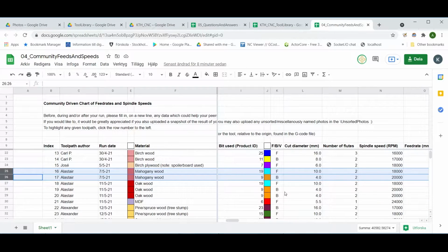And so as to make sure that the finishing of the model that we intend to mill gets an equally smooth or perhaps even smoother surface, we can use a 3D parallel toolpath with perhaps a stepover of 1mm instead of 2mm. 1mm stepover will of course lead to double the time as 2mm stepover would require, but this can be something that we evaluate during the authoring of the toolpath and simulating the results, estimating the time it actually takes to mill.